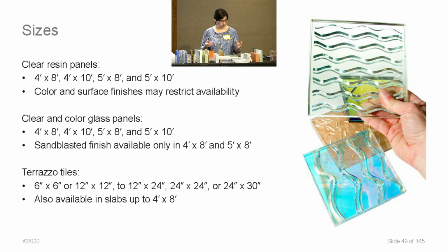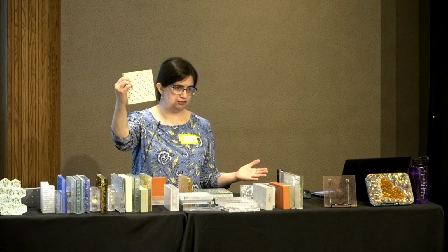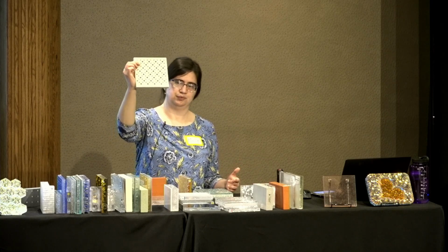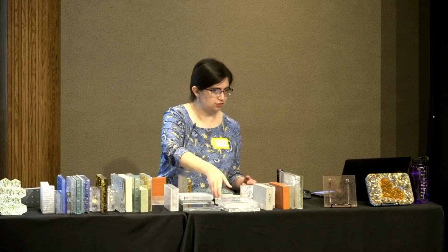And for the terrazzo, you have a couple different options. The most popular is a slab format, which is going to be fairly thick, usually an inch or more, but it's very flexible in terms of how large it can get, up to 4 by 8, sometimes larger, it kind of depends. Or you can do a tile format, which is much thinner but also more modular, like a 12 by 12 or 12 by 24, that sort of thing. And that just depends on what kind of design you're looking for.